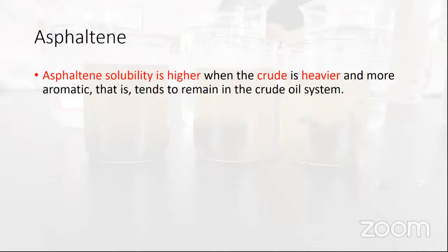Like we have a case study where we open two perforations in an oil well. One perforation is producing light oil, and the other is producing a heavy oil. So the heavy oil has some asphaltene in its composition, and the light oil's composition is mostly light saturate components. So when we open the two perforations, the two oils meet together. So the asphaltene deposited due to adding the light saturate components from the light oil to the heavy oil.